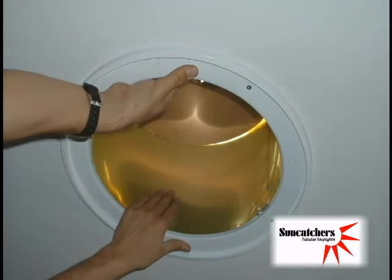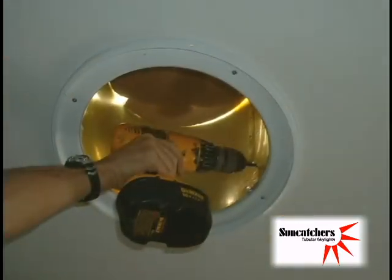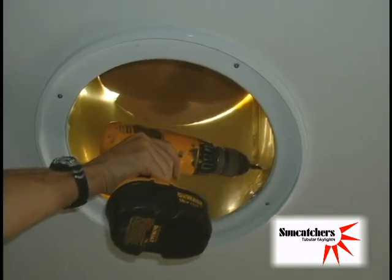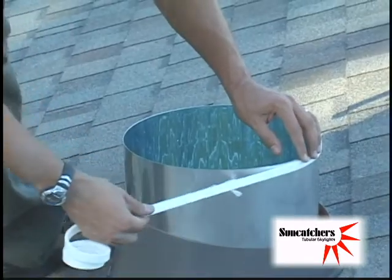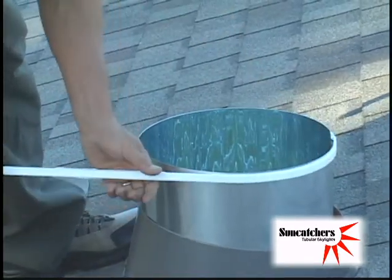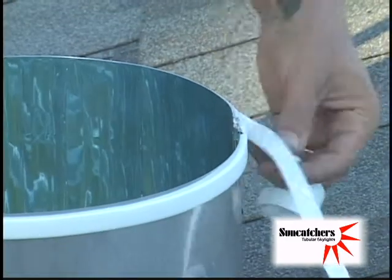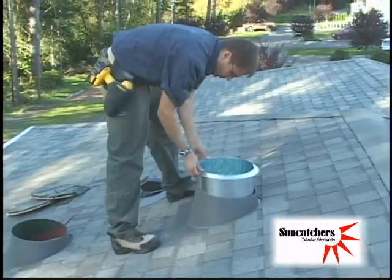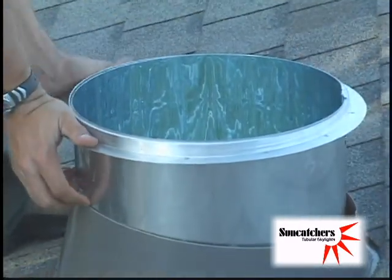Inside the house, you can now pull the pipe down flush with the bottom of the white ring and secure it to a truss in the attic using a screw of adequate length directly through the pipe. Back on the roof, apply foam tape around the top of the pipe, approximately 1/4 inch down, and remove excess material. Push the aluminum ring down until flush with the top of the foam tape.